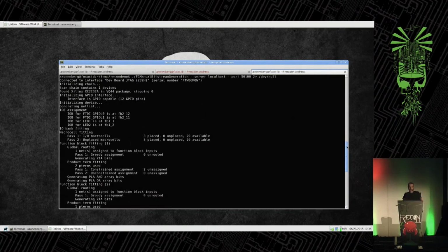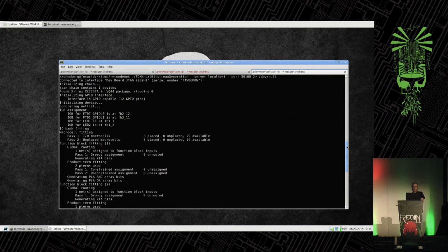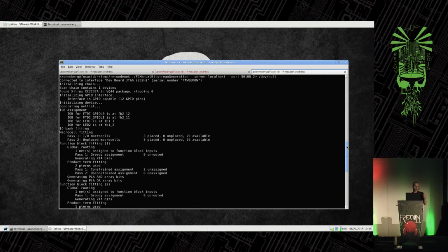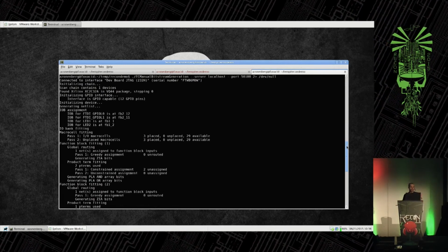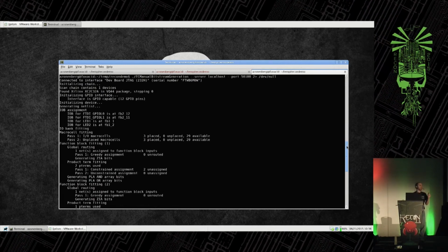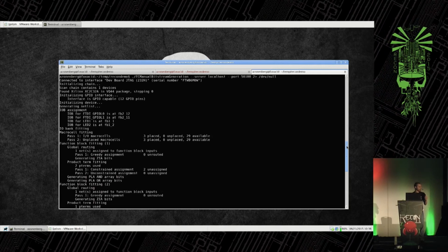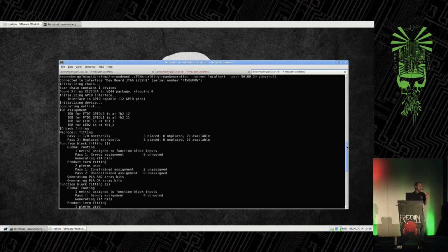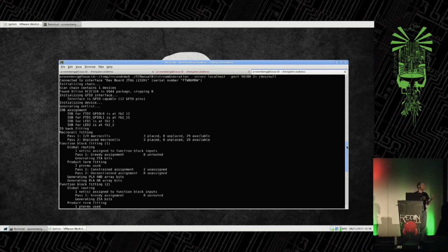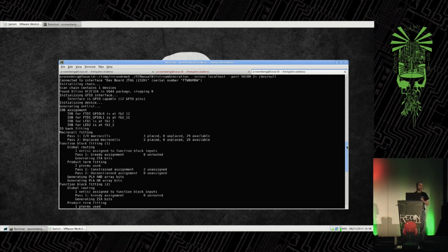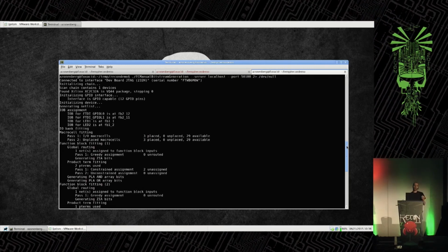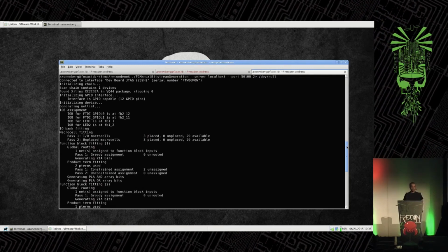you can see we start out initializing, we connect to the JTAG chain, we see, okay, there is a device. One odd note, the CoolRunners are the only devices I've ever actually looked at in which the JTAG device ID actually includes the package as well as the device. So what this means is that they've actually got a fuse somewhere in the die that says, oh, this is a TQFP, this is a BGA. I've never seen that on any other device. Every other FPGA or microcontroller or anything I've used, the device ID was the same between different packages.